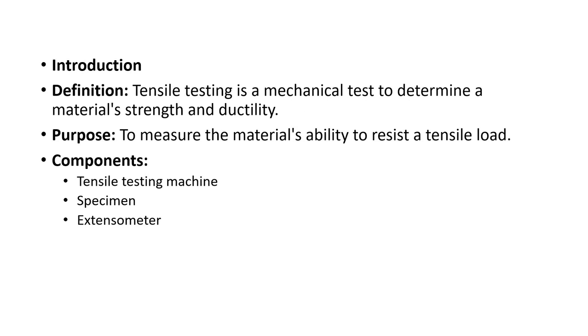First, introduction, we will study the definition of tensile testing. In this lecture, we will study destructive testing, and one of the destructive testing methods is tensile testing. Tensile testing is a mechanical test to determine a material's strength and ductility. Normally, this test is conducted to determine the mechanical properties like strength and ductility. Strength is nothing but the ability to resist, and ductility is nothing but elongation. And to measure that strength and ductility, the tensile test is performed.